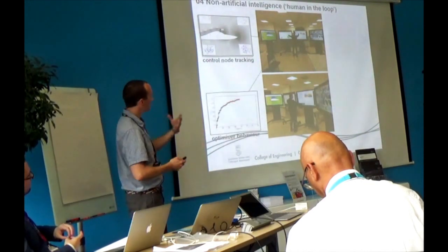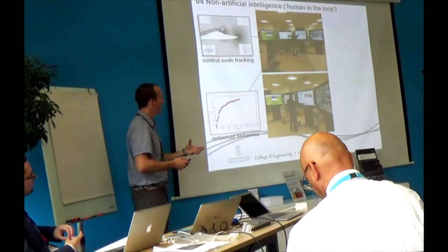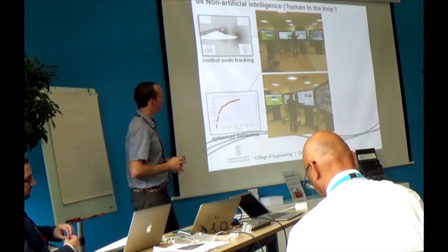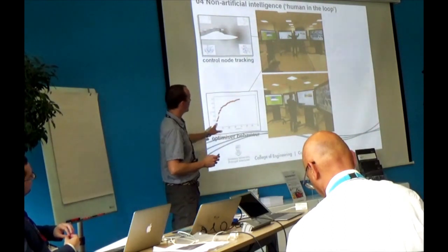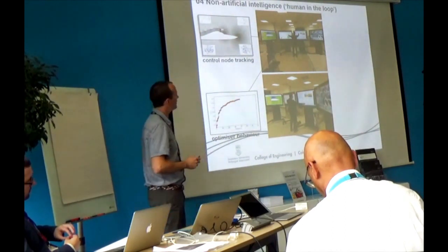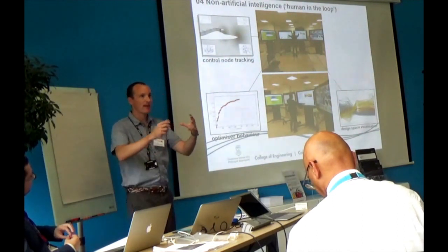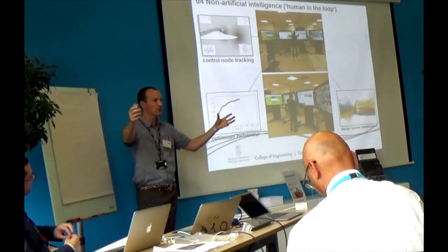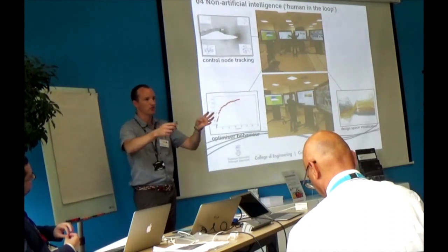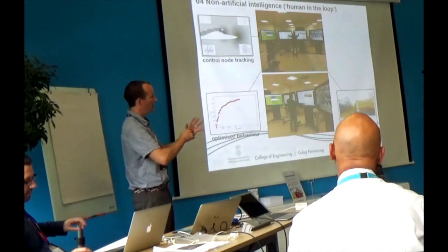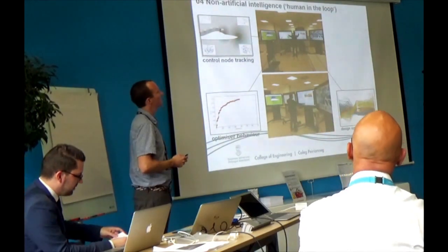How do we show that in a meaningful way to the design engineer? How are, for example, the fitness or the objective function of your best design or your worst design evolving with iteration number? Again, how do you most effectively represent how designs are clustered across a high-dimensional design space? Once you're above about 2 or 3 dimensions, in terms of the degrees of freedom in your problem, it's very difficult to intuitively show that.